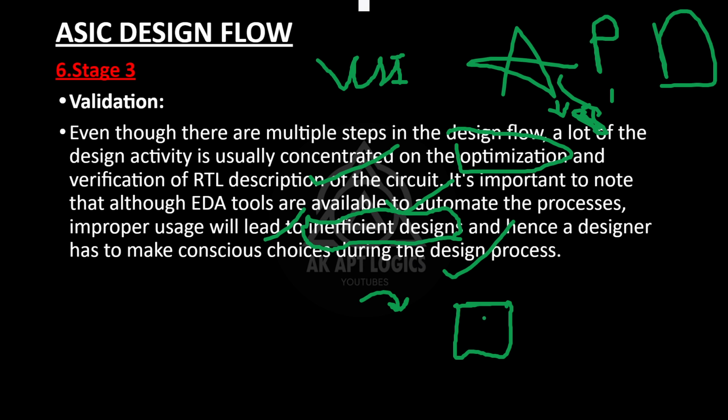because the behavioral model only discusses the high level details. It gives some random circuit. So for that functionality, we will convert that particular code into the RTL, and we again perform the verification. If everything is fine, we will generate the gate level netlist.